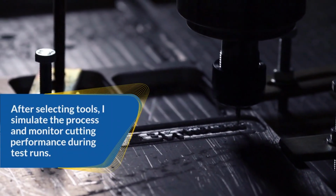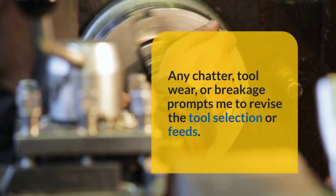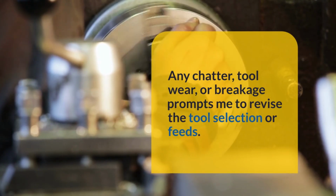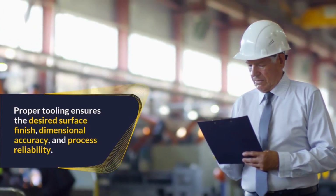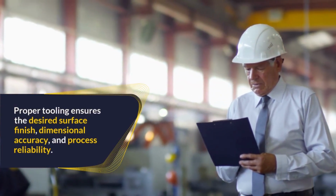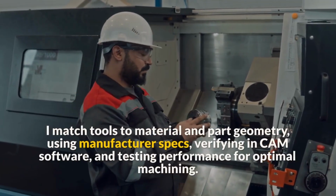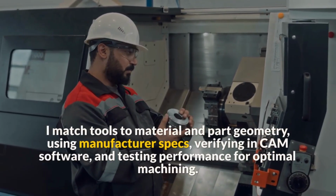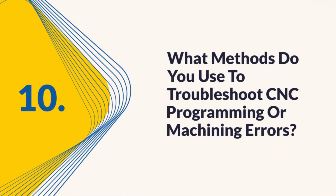After selecting tools, I simulate the process and monitor cutting performance during test runs. Any chatter, tool wear, or breakage prompts me to revise the tool selection or feeds. Proper tooling ensures the desired surface finish, dimensional accuracy, and process reliability. I match tools to material and part geometry using manufacturer specs, verifying in CAM software, and testing performance for optimal machining. 10. What methods do you use to troubleshoot CNC programming or machining errors?